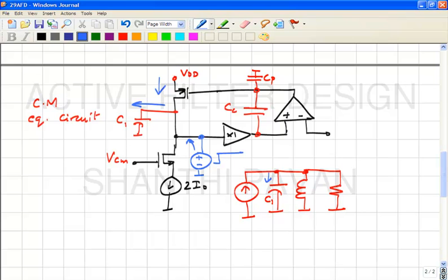So the only fellow responsible for change in the PMOS drain current is simply the change in the potential at the gate. Correct? Now, if CC wasn't around and only CP was there, then a change in the potential here will cause a change in the potential there. Correct? Because that's a unity gain buffer, which means what will happen to this guy, the error amplifier? What is he doing? He is pushing a current into CP. But what can you say about the voltage across the capacitor?